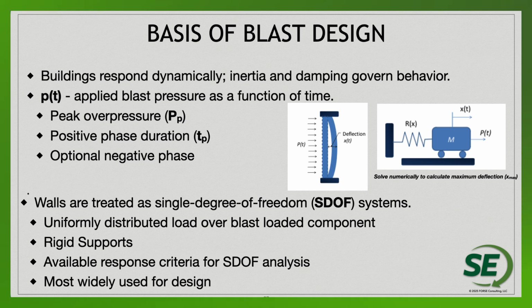The model assumes rigid supports. This is a bit conservative, but the purpose of the SDOF analysis is to numerically solve for the maximum displacement, shown as X max here in the figure, which is the key output. So it's really a deformation-based analysis. And then from there, we compute ductility and support rotation for performance evaluation. The diagram here on the right shows that conversion.